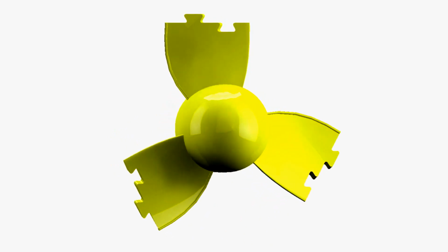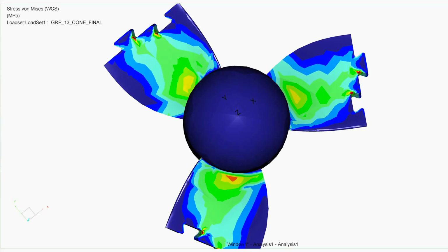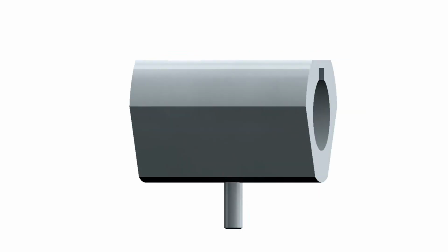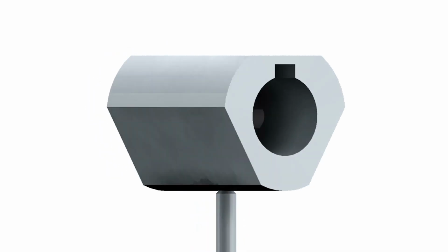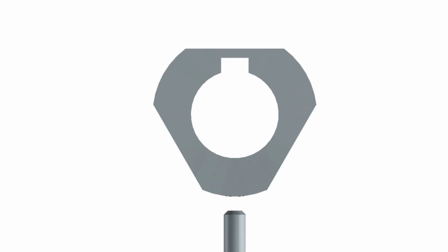The cone and the roots of the blade are designed to be printed together to ensure the roots of the blades are strongly attached to the cone. Our hub design should allow the rotor to spin freely whilst being as light as possible. We used only a hub length of 40mm since the loading during testing is exclusively rotational, so a shorter hub will not compromise the performance. A hub diameter of 30mm was chosen for the hub to be as small and as light as possible.